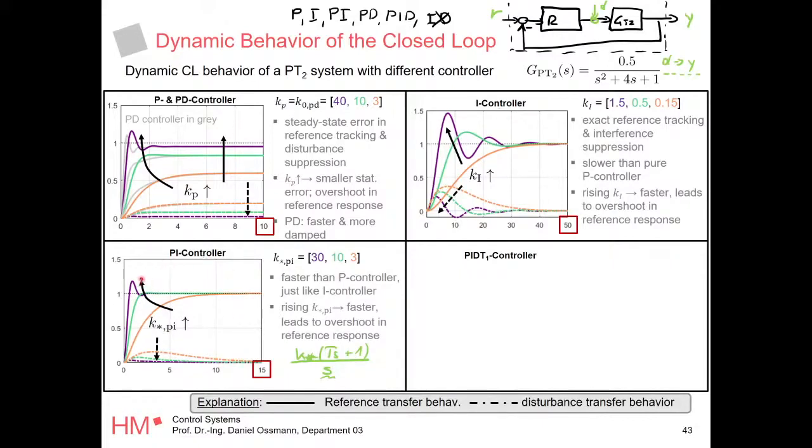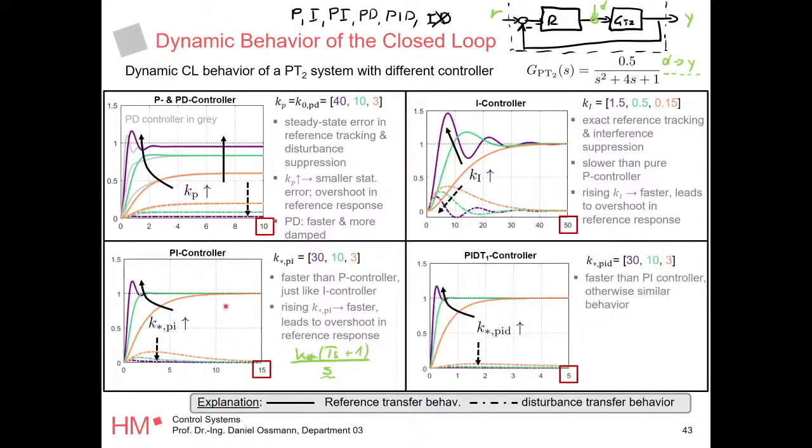So if you say now, this guy is still too slow, you can add a differentiator here, right? Here, it looks very much the same. I'm using the same gains. I'm just adding a differentiating part, and suddenly we are accurate and fast, right?